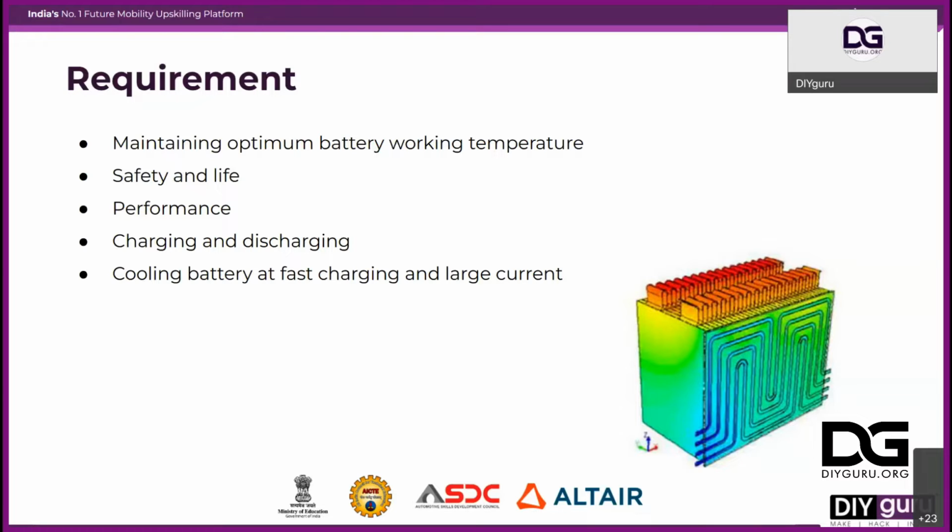Even the architecture right now followed by the Ziptron technology in the Tata Tigor EV works on 72 volt. So if they're working with a 20 kilowatt, 25 kilowatt motor and the voltage is less, it is suggestive that there will be a high amount of current. That's why these batteries work with a very high thermal management aspect. They have liquid cooling, and forced induction cooling as well. That's why these things are required.